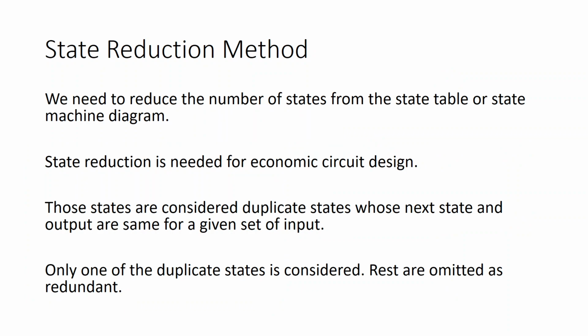What is basically the state reduction method? Sometimes we would need to reduce the number of states from either the state table or the state machine diagram, so that we come to an economic circuit design. Okay, the state reduction is needed for economic circuit design, and these are the states which are considered duplicate states.